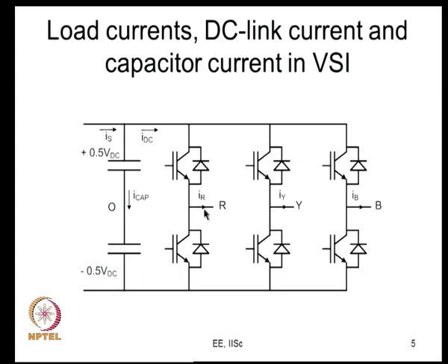As we also discussed while we were discussing voltage source inverters, we can see which device conducts. For example, you have a transistor and an anti-parallel diode in the top. You also have a transistor and an anti-parallel diode in the bottom. So, the question is who will conduct when. Let us say this is the direction of current flowing here, that is from my left to right as shown by the arrow mark here. In that case, if the top device has been switched on, the bottom device will be switched off, and the top transistor will actually conduct this current.